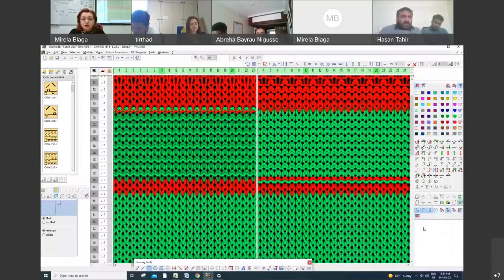The yarn properties are also important. The yarn blends are also important, but the yarns for knitting have a certain twisting. The yarns for woven fabrics are highly twisted, while the yarns for knitted fabrics are less twisted during the spinning. So the yarn properties also influence the level of rolling. But because of the loop forming process, this structure is a fabric which is rolling.